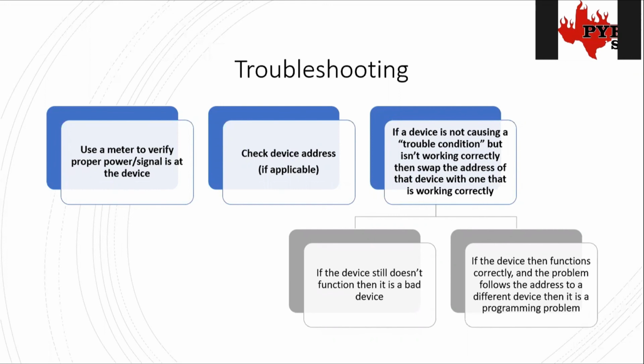Okay, that's a really good question. All smoke detectors for any application, not just elevator specific, have to be within 21 feet of all points of everything. So that's the furthest that any smoke detector is listed to be placed from. Just by that standard, it has to be within 21 feet of the door. The elevator inspectors that I've had give us problems with it want it within 10 feet of the door. I think that's written somewhere in their elevator code that they want it within 10 feet. Yeah, I know you said you were going to get into that a little bit later, have another session on that.